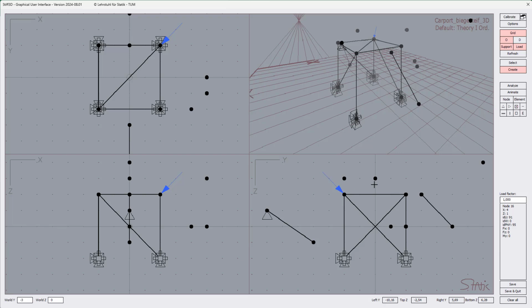And then we also have the possibility to switch on support conditions for the rotations: rotation around the Y-axis in this case, rotation around the Z-axis in this case, or if you switch into here, the rotation around the X-axis, which again is this indicator here, which in this view will be this filled little square here. Which means rotation around the third axis, which in this view is the X-axis, equivalent to this direction or that direction, for the respective views.